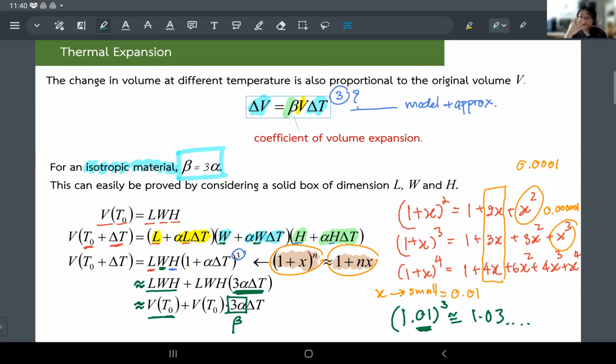So what about material with thermal shape memory? That's crazy stuff, because when you say thermal shape memory, it means it has a rigid structure at one particular temperature. Every time you change the temperature, it changes the shape. But if you bring it back to the same temperature, it will come back to the original shape. Or you might have to erase some memory first, warming it up until it forgets everything, and then cooling it back down. Once it reaches that original temperature, it will come back to the original structure.